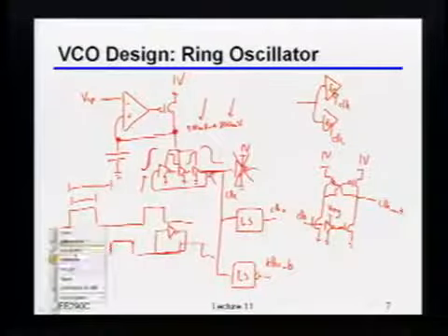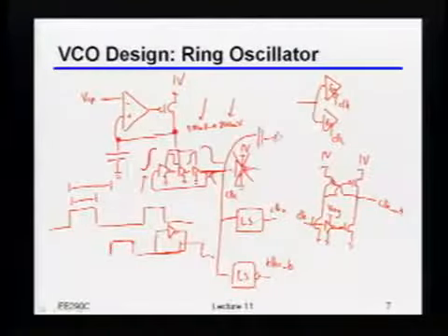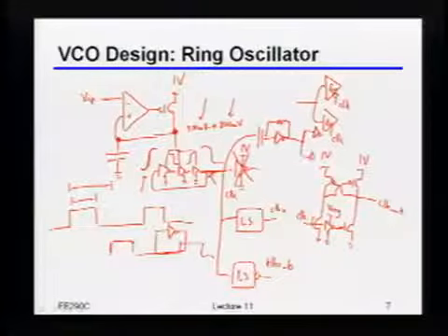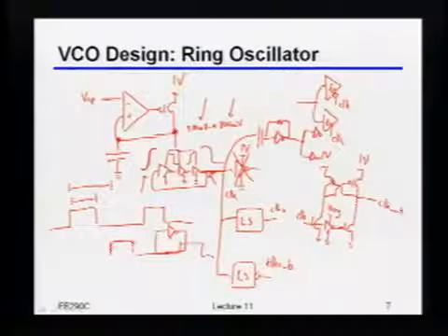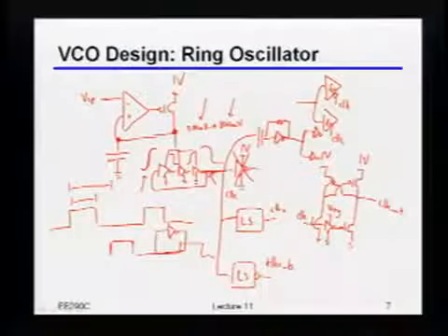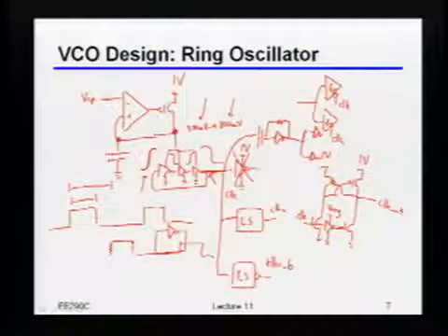What you can also do, which is slightly more common, is you could just have one level conversion path, let's say something like this, right? And then phase split at least in the full supply domain, so that you have less variation in terms of what you have to deal with on that phase split path. But again, there's actually no perfect way of doing this. Okay?